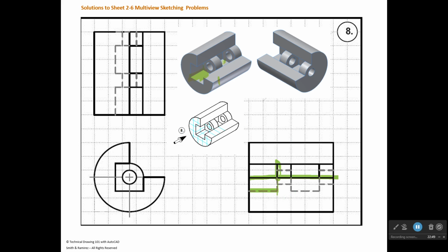Then you have the same thing on the opposite side of that. You have a visible line here going into a hidden line, and then a flat plane coming across that's hidden from you that also goes up as a hidden line till it gets to that horizontal line and then comes out as a visible line that's vertical.